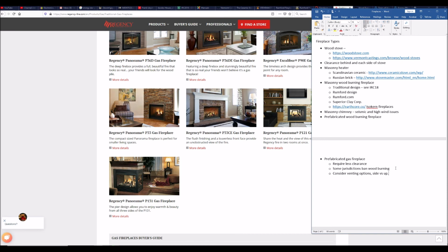And so you want to place that in a location where it's not going to be easy for people to bump into, for children to be tempted to reach up and touch. Just a little thing to keep in mind. You mustn't forget that there's something on the other side of the wall there when you're putting your fireplace in. And that goes to say that if you're putting it in the middle of your house somewhere where it's far from an outside wall, and if it's on the ground floor of a 2-story house with an attic, you may get into issues with how long your chimney is. So that's another point to keep in mind. Too many bends, you can't have too many bends. There are limitations as to how far you can go with the flue.